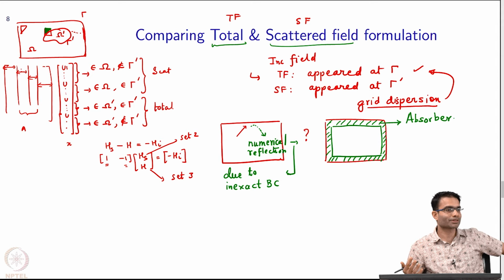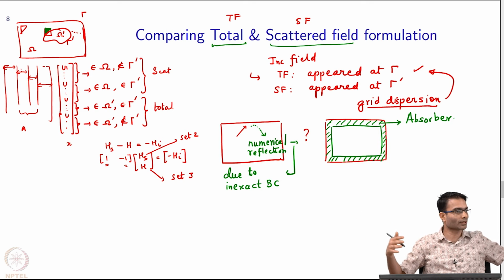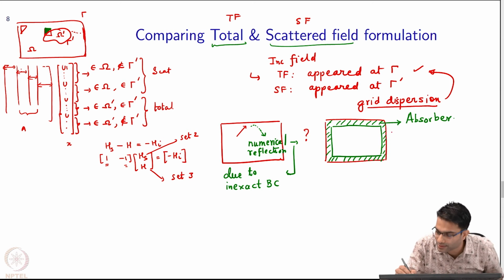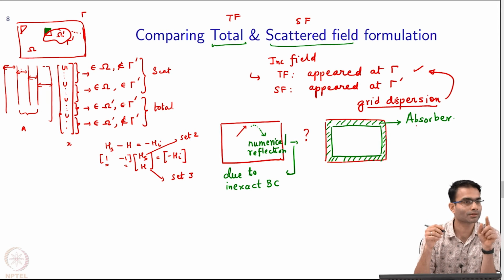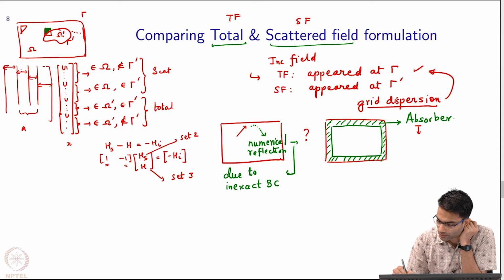It's an absurd question. The skin depth is infinity. The wave never decays in vacuum, right? Vacuum has no loss, it goes on forever. The moment I introduce some loss into the thing, that is conductivity, the wave begins to decay. So that's the hint. How do I implement this absorber mathematically? Well, I just create in this green shaded region, I introduce loss in the epsilon r mu r of those triangles. So over here, I can say epsilon r, make it lossy.